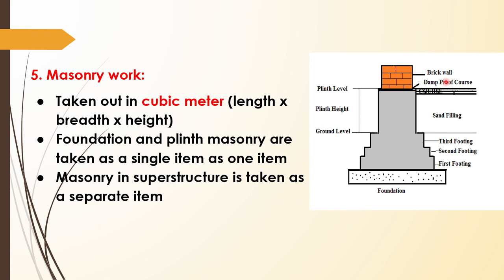The damp proof course is provided to reduce the moisture absorption of the brick wall or the wall which we are providing. Okay. Now, moving to the masonry work, we have to provide masonry in foundation as well as in the superstructure. So up to this portion it is foundation, and above this it is superstructure.